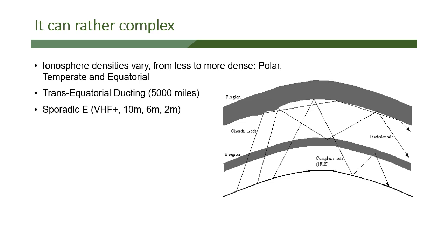We also have sporadic E, which I mentioned earlier, which is a very transient, localized phenomenon that happens in the E layer, where because of solar weather, a specific area of the E region has become more energized, and so energized that the VHF frequencies around the 10 meter, 6 meter, and 2 meter area can now be reflected back down to Earth, which extends the range of those communications across the globe. Usually 600 to 1,200 kilometers is not unusual. On 10 meters even more, but I was just talking about 2 meters. But on 10 meters, it can be much longer.